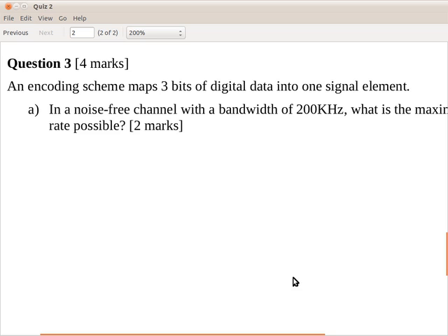So what that means is when we want to transmit digital data, a sequence of bits, if that's our data we want to send, our scheme to map the data into a signal takes 3 bits, and that maps to one of 8 different levels. Why 8? Well, the optimal scheme, if we're going to work at 3 bits at a time, has 8 different combinations.